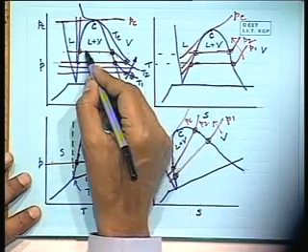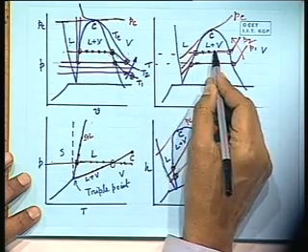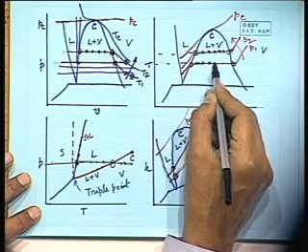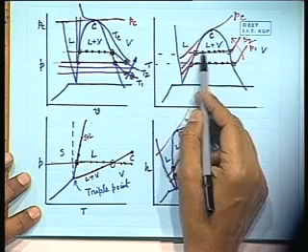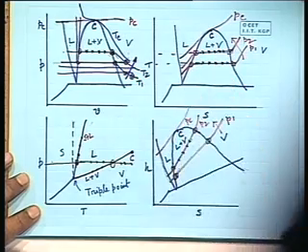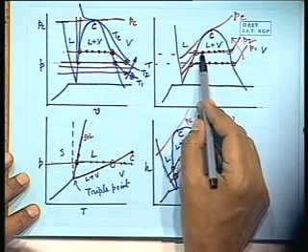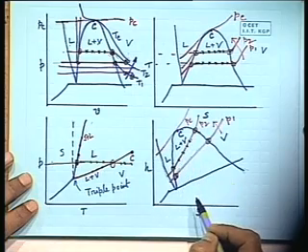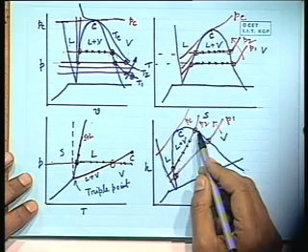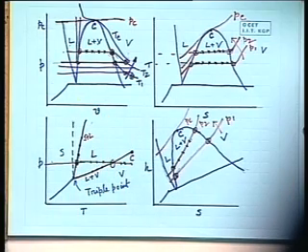But now the question comes, what are these state points which show different values of specific volume, specific entropy or even specific enthalpy, but at the same pressure and temperature, that means within the vapor dome? The different points within the vapor dome showing different values of specific volume, entropy, and enthalpy, but at the same pressure and temperature, indicate physically a mixture of the two phases, and the mixture composition is varying.